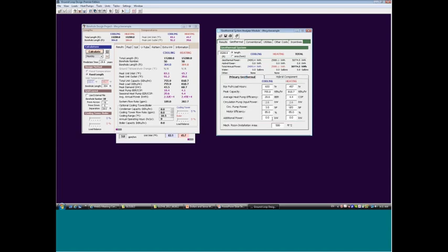When we imported this in, we have some numbers that come up here. It shows me my predicted kilowatt hour consumption for my cooling side of my geothermal system and my heating side and my totals. There's no hybrid power, so that's zeroed out. I have my total annual power here. There's no water being consumed, and there's nothing else being consumed because we haven't added anything else in. Other things would be things such as therms of natural gas, tons of coal, et cetera, et cetera.